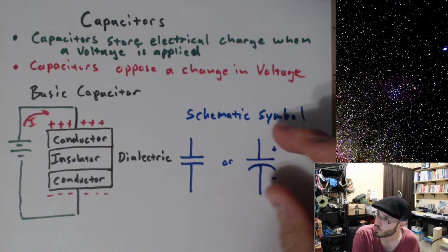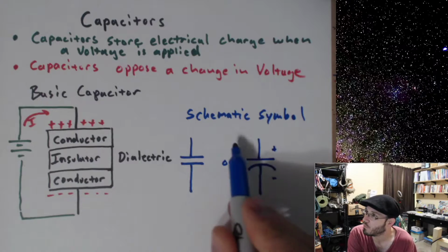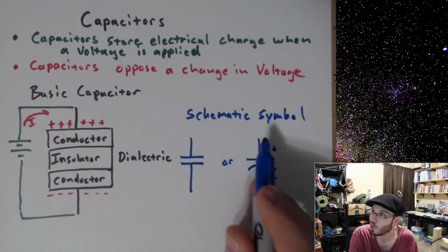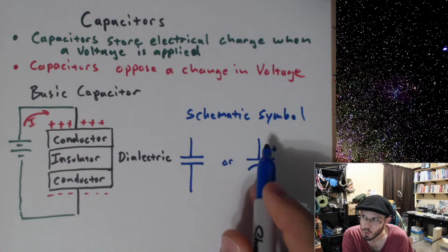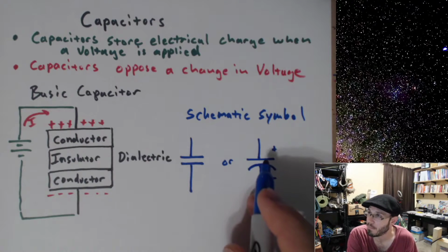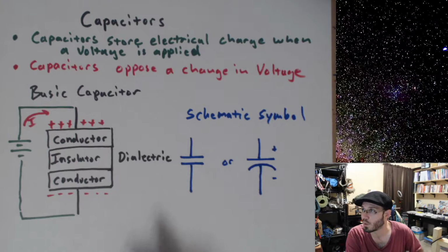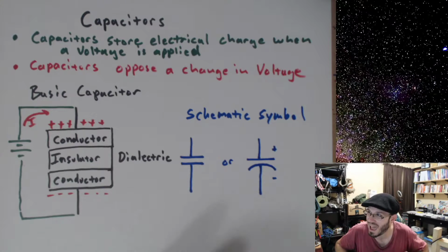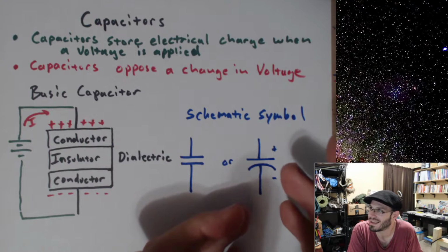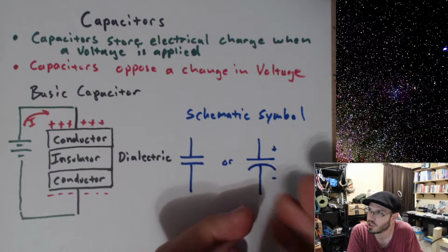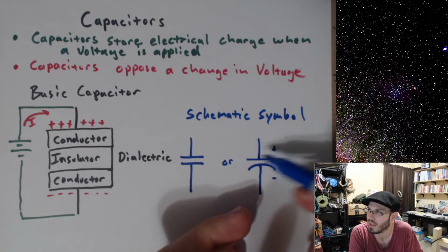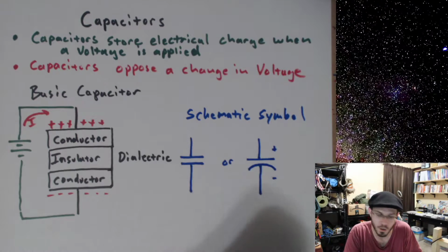Now, if we were to reverse the polarity, meaning if we had this bottom side attached to the higher voltage and this was the lower voltage, the cap will still work for a period of time, but eventually it's going to break down. And that's not because capacitors require having polarity, but because of the type of capacitor, you have to deal with some physical limitations, and so we're required to connect it such that the higher voltage is on the flat side and the curved side has the lower voltage.